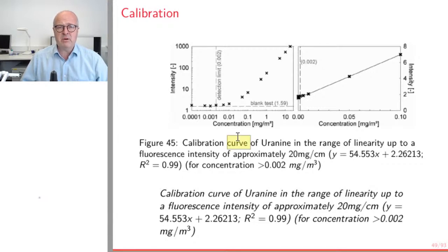So if a trace experiment has been done at this site before, then you can still find some uranine in the groundwater. So you should check the database for previous experiments, and you should always use your substance carefully, and you should never use the substance without indicating it. First of all, it's illegal, and second, you might spoil the trace experiment of somebody else.